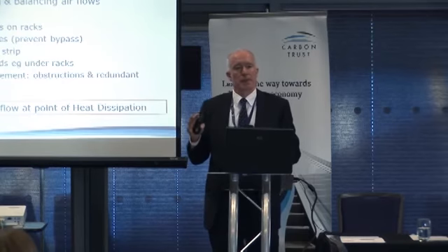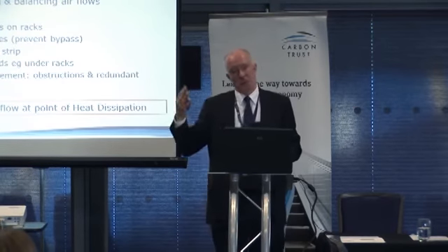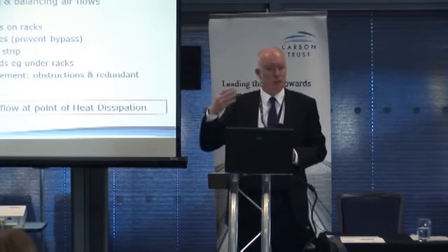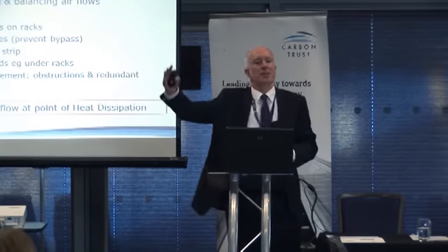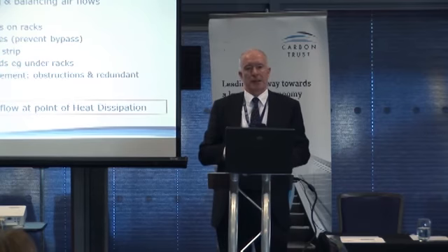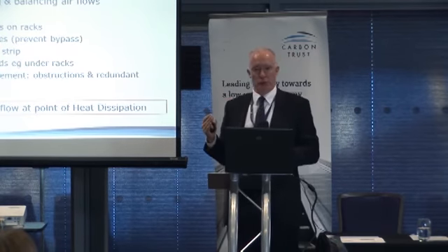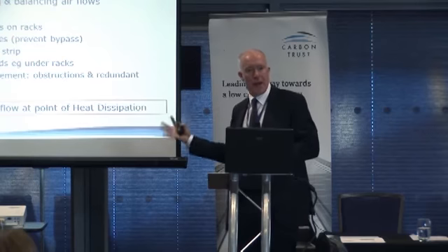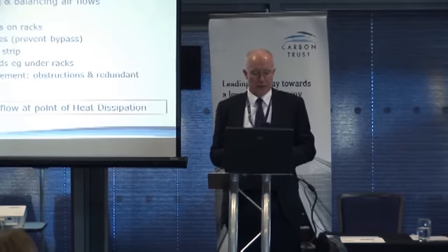The other thing is to try and make sure that the airflow is right, and we do this with measuring with anemometers, hot wire anemometers, vane anemometers, to make sure that the airflow is right and going through the computers. Lots of simple things. Racks often have doors on them. Get rid of those doors. We want the air onto the computer. We don't want any resistance here.